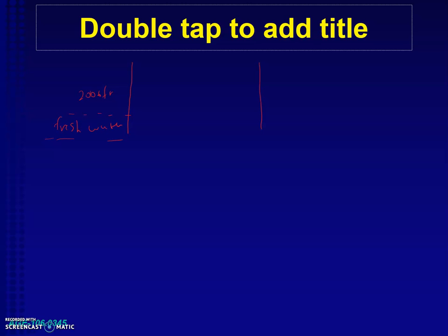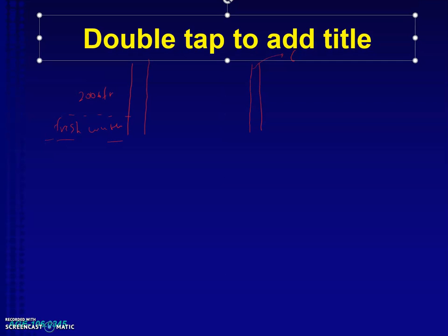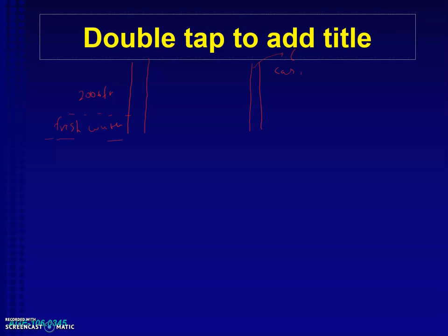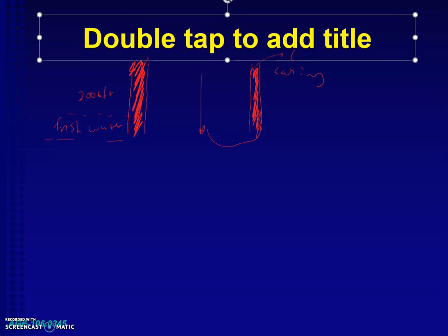In order to do that, you put a piece of pipe inside the wellbore, which is called casing, and then you inject cement into the wellbore, and this cement will go to the annulus and fill the annulus. And then you wait until this cement is set.